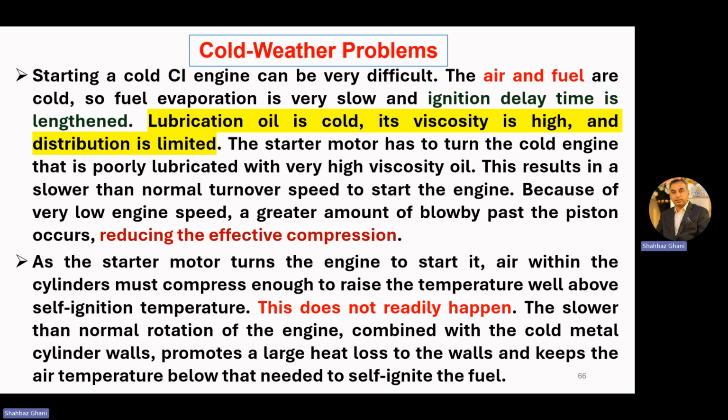So now the last topic of this combustion is the cold weather problem. Starting a cold CI engine can be very difficult. The air and fuels are cold. Engine is cold, air is cold, fuel is cold. So fuel evaporation is very slow and ignition delay time is lengthened. When fuel is evaporating very slowly, the ignition delay time will be more.